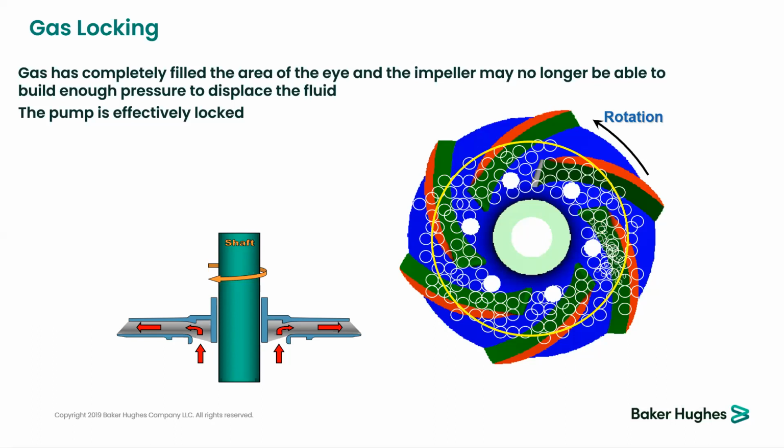In that schematic, you can see a fairly clear separation between the liquid and the gas. This is not actually true, but it's an illustration of what happens inside the process of gas locking, in which the liquid and gas mixture will not be interfaced in dynamic operation. The gas-liquid condition will last until a pressure change occurs, and then it will break, and the impeller will charge or take in liquid again, which happens either manually or automatically.